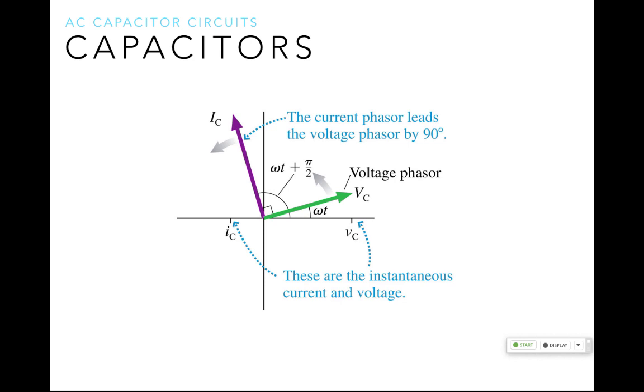The voltage and current through your capacitor have this lead because as you're charging up your capacitor, basically, as your voltage source goes up, it takes time for your capacitor to go up. So the current across the capacitor gets ahead of the voltage source, okay? So your current leads your voltage by pi/2, or 90 degrees. This phase difference is introduced by the fact that there's a delay as the capacitor reacts to what's going on with your voltage source.